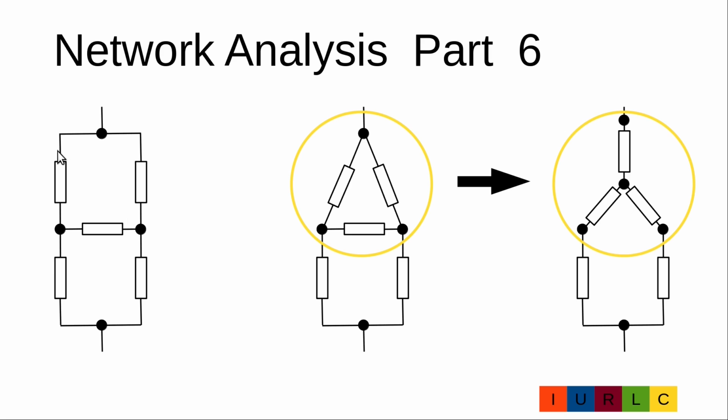parallel formula because these parallel resistors are linked with a serial resistor, and we cannot simplify with the serial formula because these two serial resistors have some link from the inner node to some other point. To solve such kind of problems, we need the delta-to-wye transformation.